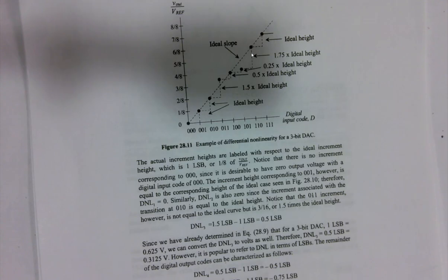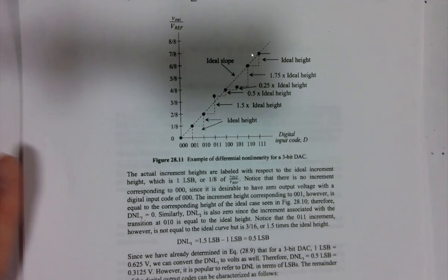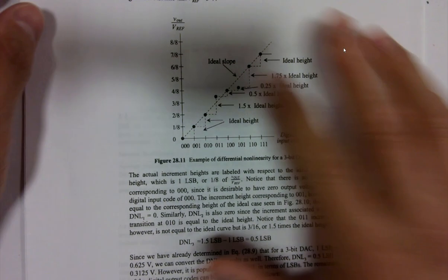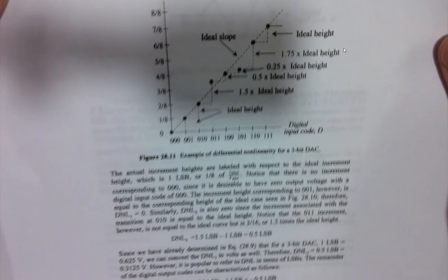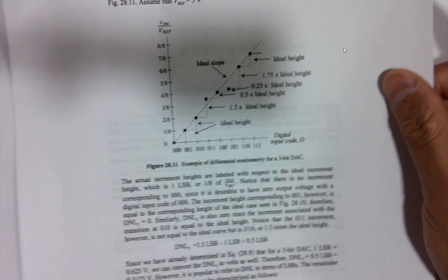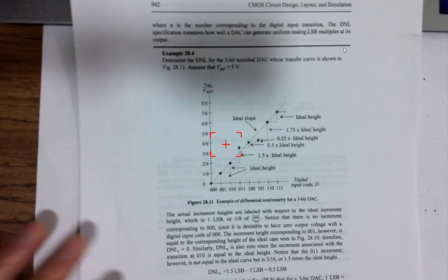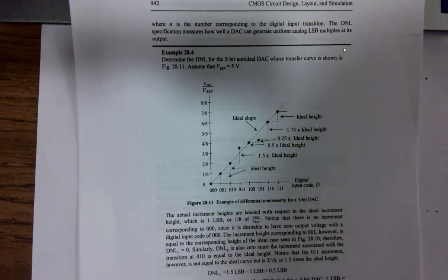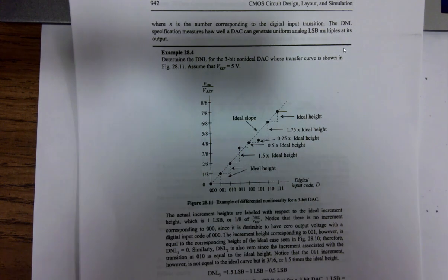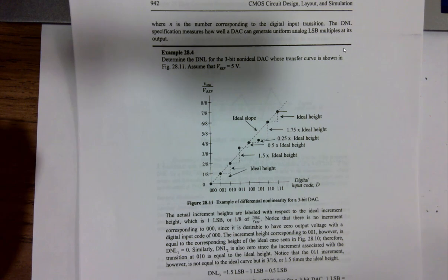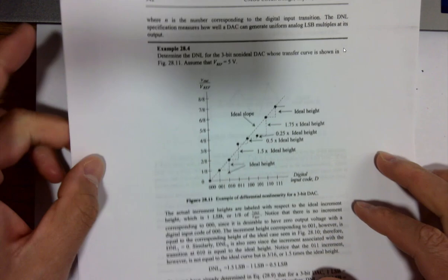But for the DAC, you can see DNL is called differential. You can write it down since I don't think they spelled it out. So it's differential nonlinearity. It's called DNL. This could be an interview question. We'll ask you, hey, what's the DNL and INL of your ADC? So differential nonlinearity is called DNL. And the way to calculate it is like this.